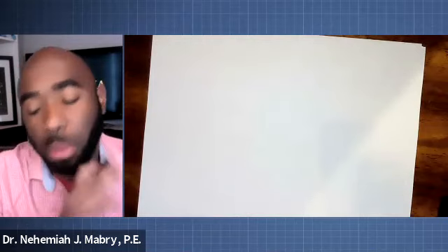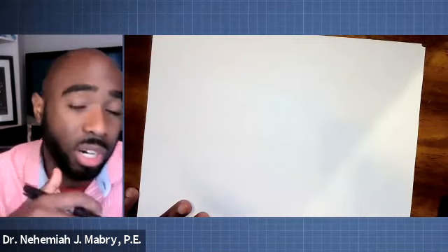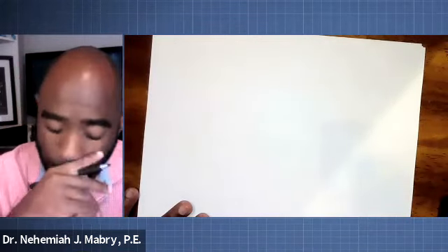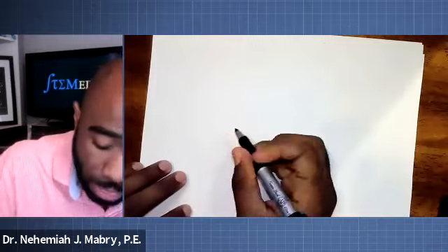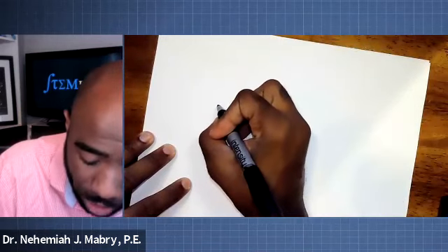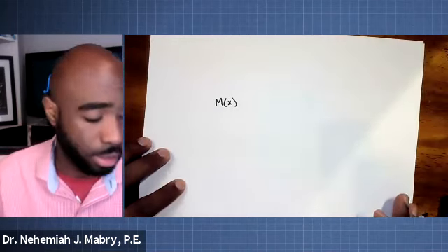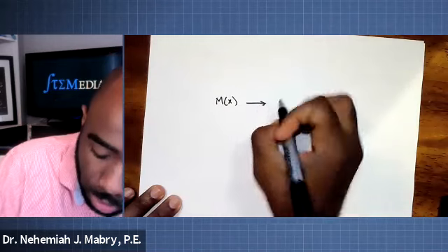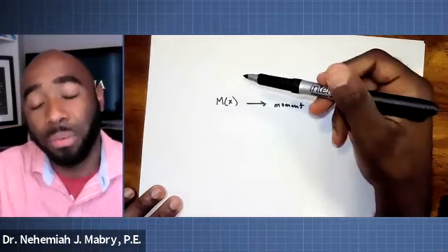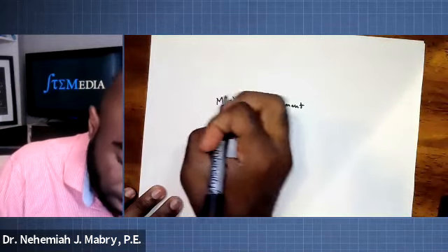All right, so here's some things you need to remember. I touched on this before in previous videos, but there's a relationship between shear, moment, the load, as well as slope and deflection. So check this out. The moment is the antiderivative, or the integral, of shear.